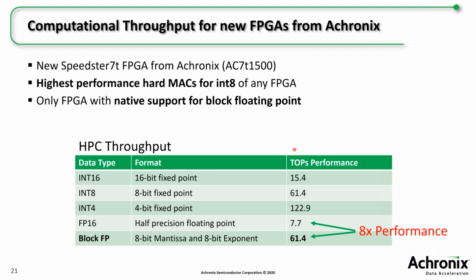And you can see that at 61.4 teraops of int8, that's the highest FPGA multiply accumulate block of any FPGA that's publicly announced on the market at the moment. So any of the devices from us or from Xilinx or from Intel, this is the highest performance for int8, and int8 obviously being a great application for machine learning inference.